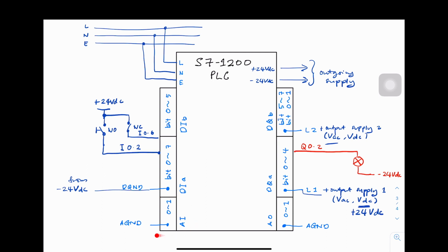The function of the analog input channel is to get measurement from a transducer. Some examples of transducers are temperature transmitter, pressure transmitter, flow transmitter, and even level transmitter. A transducer or transmitter provides an analog value, most commonly in terms of voltage or current. It can be between 0 to 10 volt for voltage or 4 to 20 milliamp if the measurement uses current.